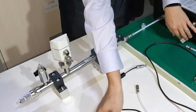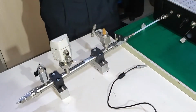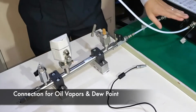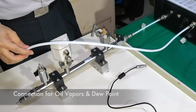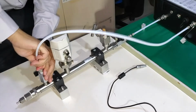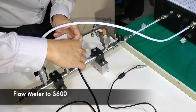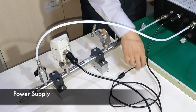Secondly, we will grab the longer Teflon hose and we will connect it to the dew point and oil vapor sensor. Then we will connect our flow sensor directly to our S600 unit so we can achieve the proper flow rate. After that, we just need to plug in the power supply.